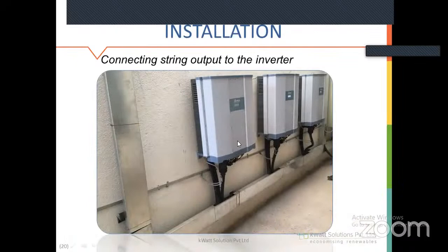So for example, if you have a 230 kilowatt plant or 1 megawatt plant, you will take 200 kilowatt peak string inverters, 5 numbers for a 1 megawatt plant. Let's say it is a 230, so I will take around 150. So I get 250 kVA solar inverter. So I have inverters over here.